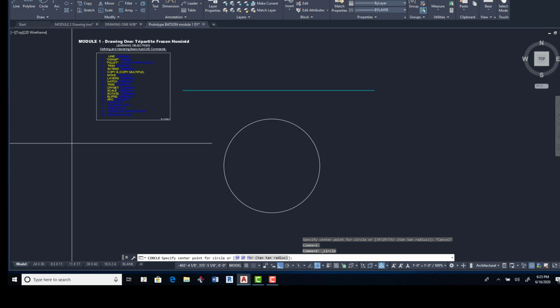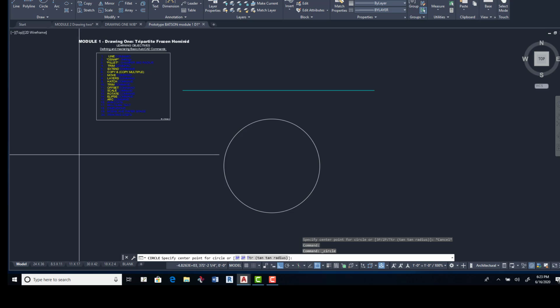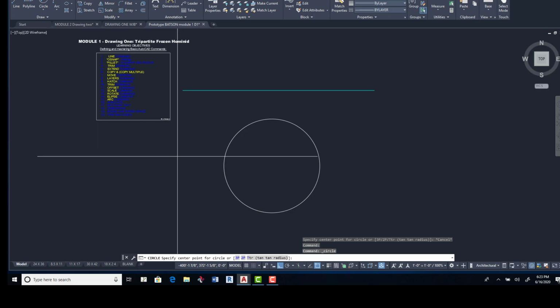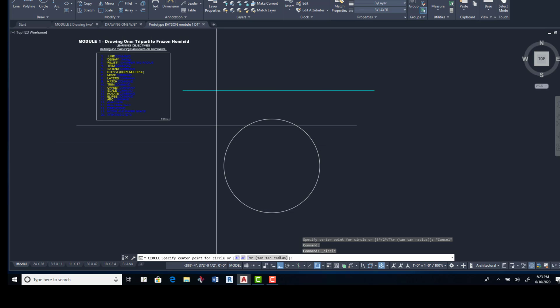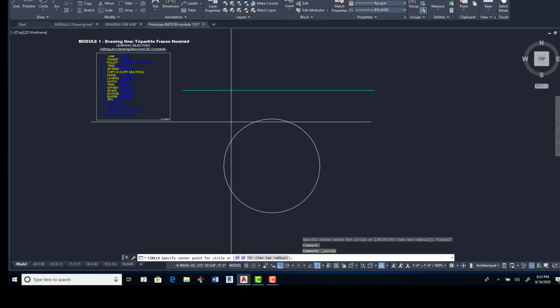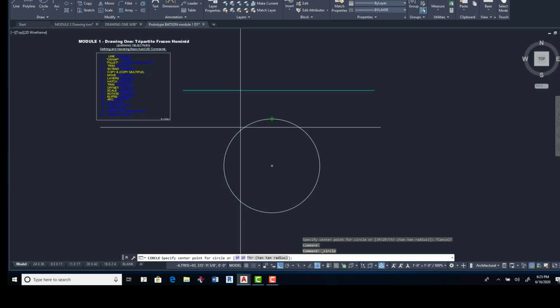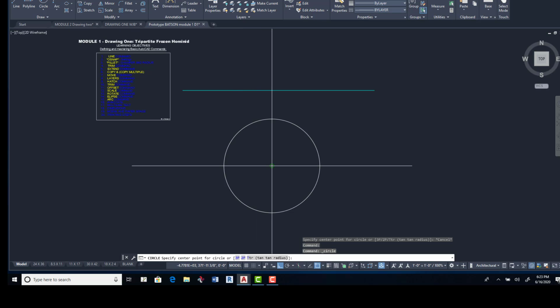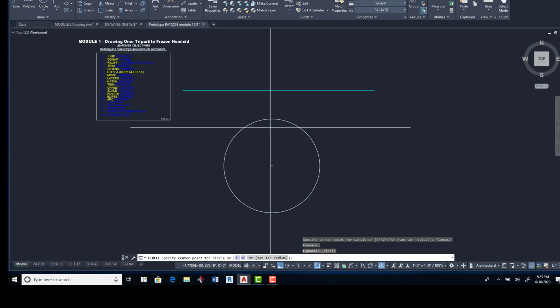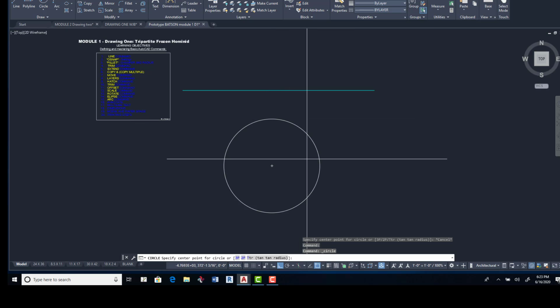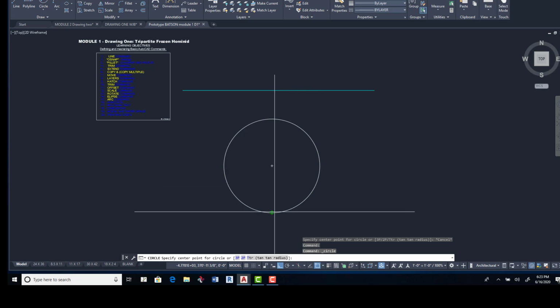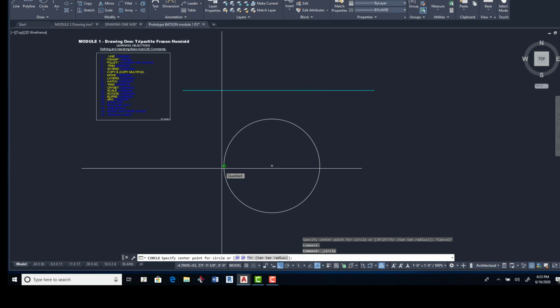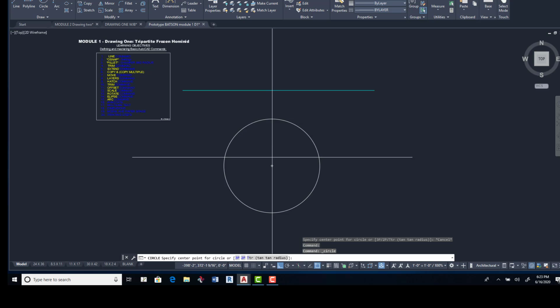Now, because you've checked the center snap, AutoCAD is going to calculate the center before you even get there. So just hover. As soon as you get to the edge of the circle, watch a crosshair show up in the middle. Watch. There you go. So a crosshair showed up here, and then a circle there. That means circle means center. And look here, there's a diamond. That means quadrant. See that diamond, quadrant, 3, 6, 9, 12 o'clock. So quadrant you're going to need too.